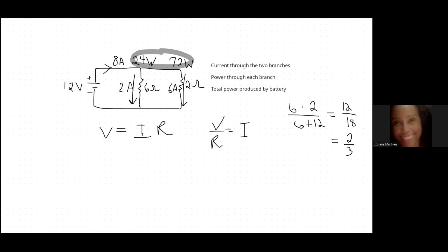That's always true. That formula, the parallel formula for resistors or the series formula for capacitors, always has that property that the final answer is always less than the smallest value in the system that you use the formula for. It's kind of cool when you think about it, and it's a good way of checking your work. All right, so now that I have the total resistance, I'm going to use Ohm's law to figure out this power again. And it actually just validates all of our formulas.